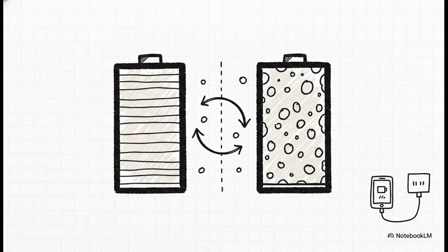Now, let's shrink things way down to the smartphone sitting right there in your pocket. That device relies on a lithium-ion cell. Interestingly enough, it doesn't actually contain metallic lithium at all. Instead, it relies entirely on the movement of lithium ions. Notice how the positive electrode is made from layers of lithium cobalt oxide, and the negative electrode is made of layers of highly porous graphite carbon. They sit in a polymer gel electrolyte completely separated by a perforated plastic sheet.